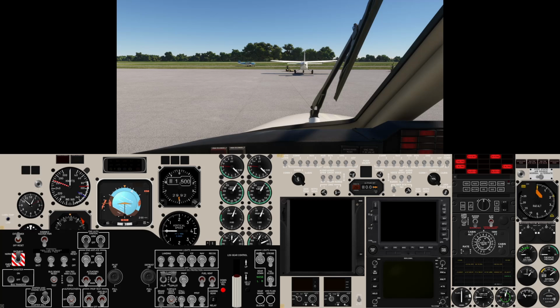It's normally, depending on the aircraft, somewhere between about 12 or 20%. There you go. Up to about 20%, then we'll put the fuel in, and then we'll just keep an eye on the ITT there, make sure it doesn't go above the start line. It doesn't. Start looks like it's about 1,000 degrees there,